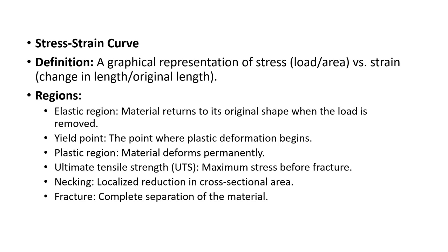That ultimate tensile strength is nothing but the maximum stress, that is the ultimate stress before fracture, meaning the material will fracture, completely break, and that strength is nothing but the ultimate strength. At that stress the component will fail, and normally for brittle material the ultimate tensile strength is taken into account for designing material.